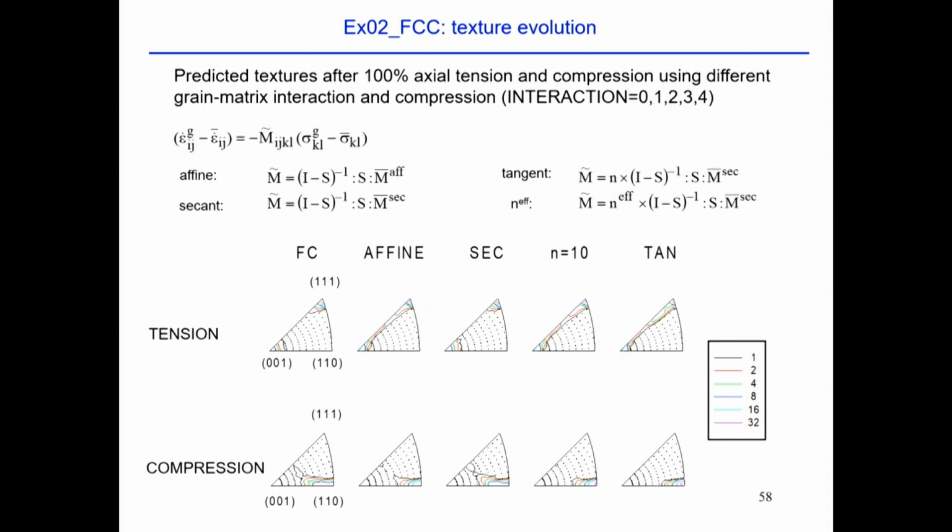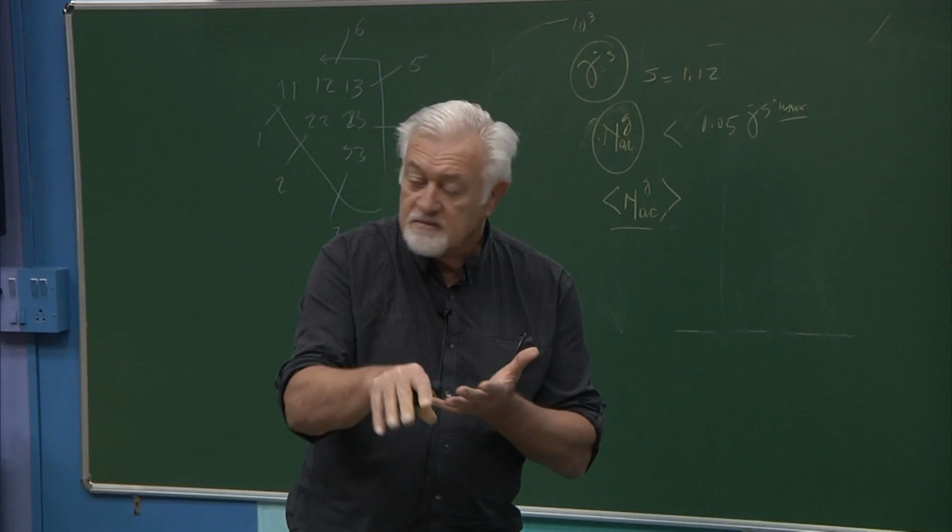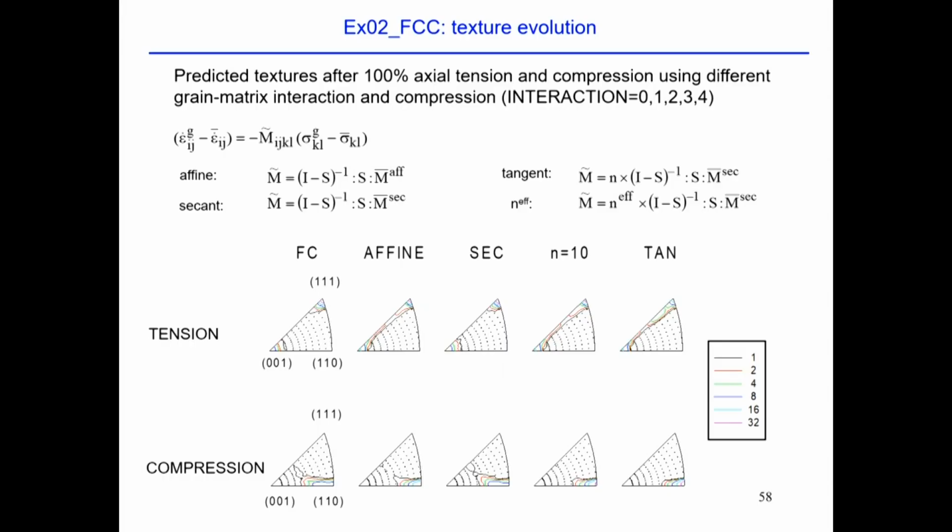You see there is a shift here that is not there. Well, that has to do with the effect that I was explaining before. That in more compliant cases, or when the medium is more compliant, the grains don't want to deform in axisymmetric deformation. They want to deform more in plane strain, and so that is what leads to this difference in texture.